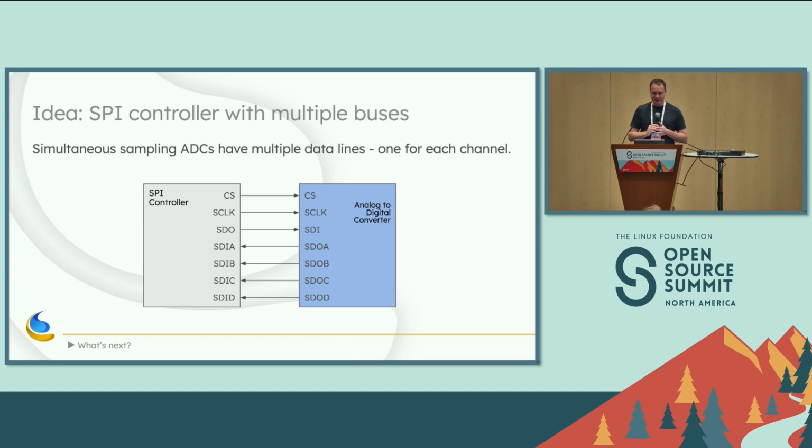And one last thing that's on my radar, that we're talking about, is how to get more bits per second over a SPI bus. This isn't exactly related to offloading either, but if you're looking at this picture and you've seen a quad SPI before, you might think this is like a normal quad SPI, but no, it's not. So this is actually what we call a single SPI controller with multiple SPI buses. So in typical quad SPI, if you've got 4 serial lines, you'd be reading 4 bits of one word all at the same time. But this is different because